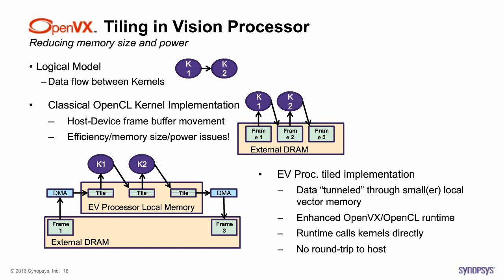What that does is allow us to read the frame once, and more than likely we don't ever have to write the frame back, because typically whatever's fed back wouldn't be the full frame, but coordinates or some other information that would be used by another portion of the system. This becomes very efficient in terms of memory, power, and bus bandwidth, because we only read the frame once, and we read it through a little bit at a time.